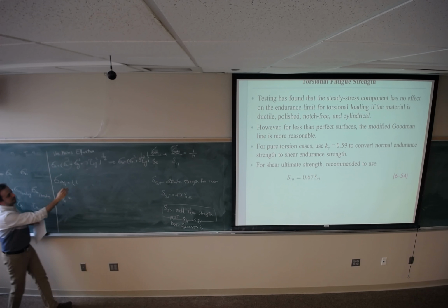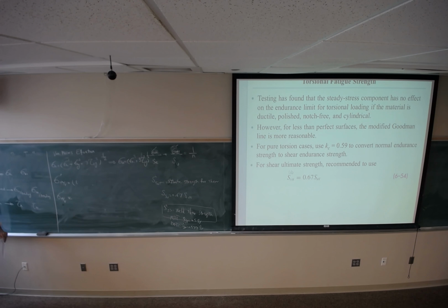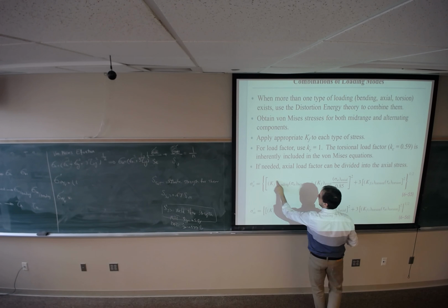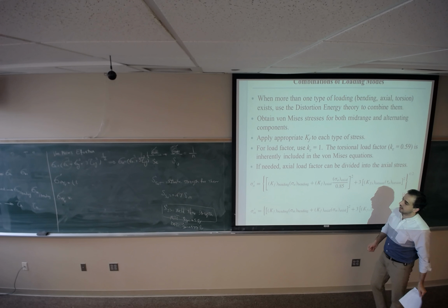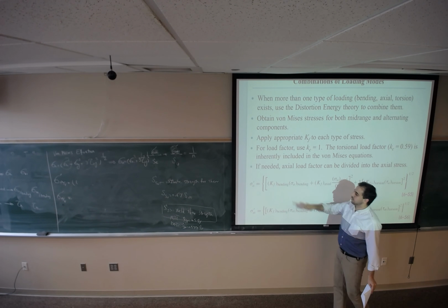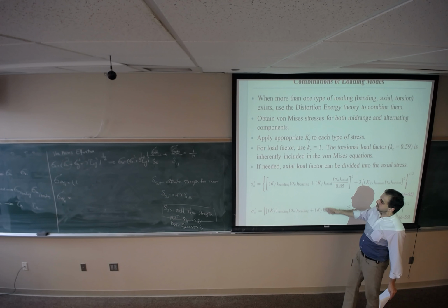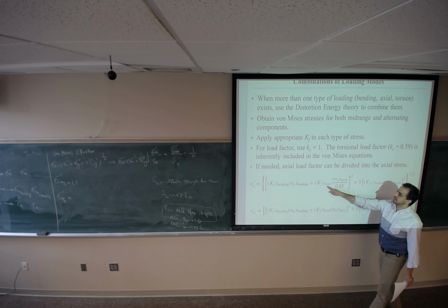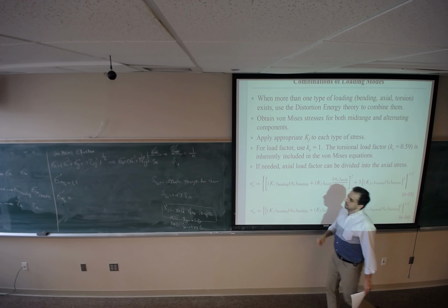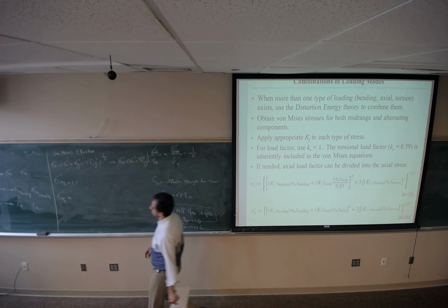But we are gonna have some other factors incorporated in this equation. It's starting from the fatigue concentration factor for bending moment. If it's involved, we should multiply this by sigma A. For the axial, we add Kf for the axial times this. We should divide by 0.85 because it's axial.